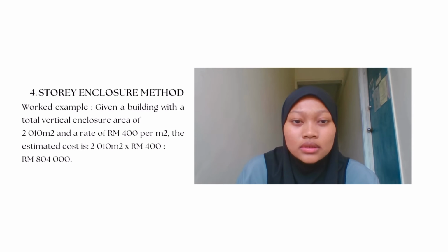Finally, the storey enclosure method. This calculates the cost based on the total vertical surface area of all floors, including walls and partitions. It's a very handy tool for multi-storey office blocks or apartments, though it does lack details regarding internal finishes.